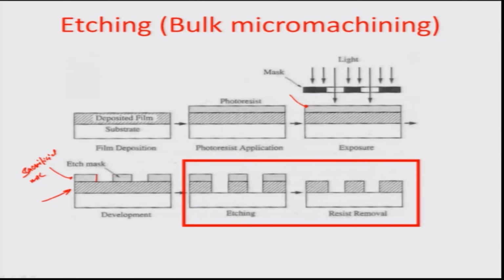So the sacrificial layer merely provides windows or regions across which such exposure can happen selectively. So the etchant can rush in through these windows and then can affect the hatched layer, and you can see the hatched layer go away here, so that you are opening this hatched layer for further etching on this particular surface. So the idea is that you have a material which is acting as a hard mask, a material which is the soft mask that you have made for etching, and through the soft mask you are imprinting onto the hard mask and using the hard mask for doing further high aspect ratio etches into the final structure. So that is how you do bulk micromachining.